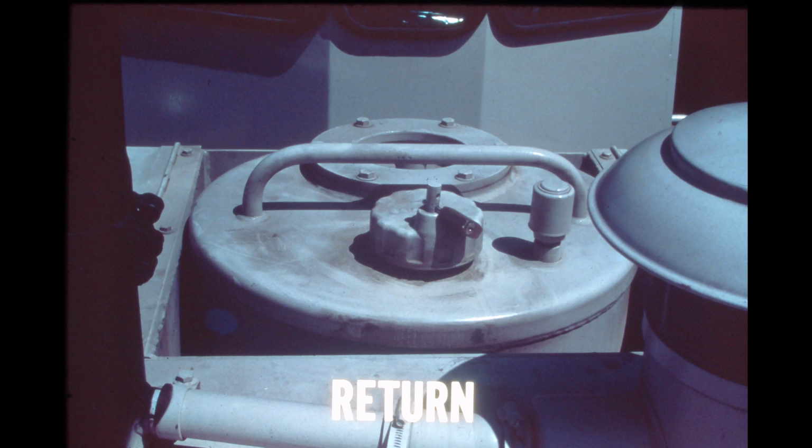The return area consists of all the components from the cylinders to the reservoir. A failure of one of these components will cause an engine overload or the hydraulic oil to overheat. The problem in this area is caused by a restriction of the return flow. The components in this area are the oil cooler, the orifice block, and all of the return lines.